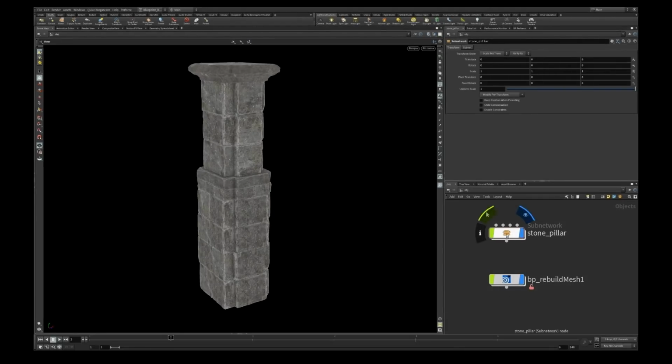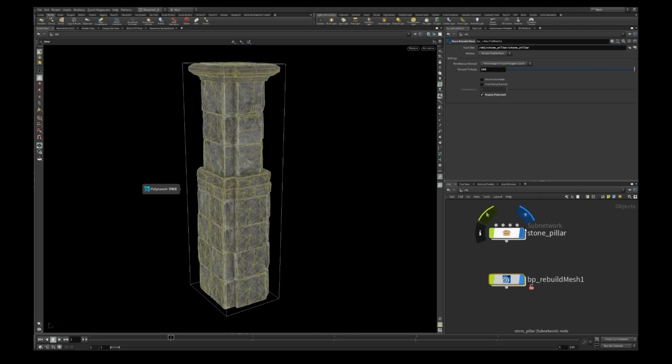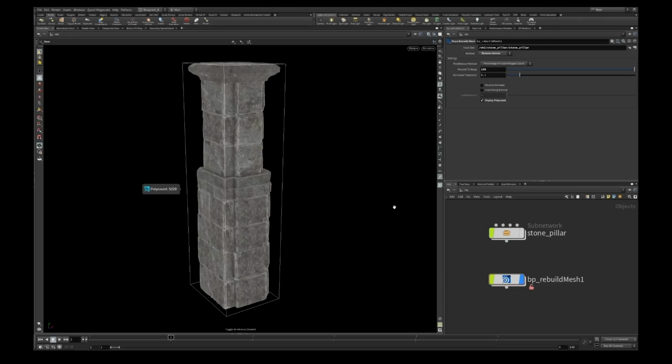Okay. So here's an example of a type of HDA. I threw a whole bunch of settings in here as a one-size-fits-all solution for an artist, so they can just bring in the mesh that they want to clean up. I don't know if you can read that number, it's just displaying the poly count on screen. We can see it took out all this nasty geo. I've got a setting on the HDA to remove interior geometry. Basically this checks for occluded geometry, occluded points, and then culls them. So there's no more cleanup and the artist doesn't have to do anything. It's just a one-click button fix.